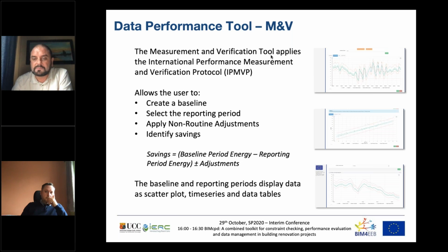The options you see on the right, in the middle, show a simple linear regression model, and the user has 2 options: when they look at the data, they can see it's either simple linear or change point based on how it's modeled, and they can save that baseline so that when they come back after the renovation, they can run the reporting period analysis, which will give them the approximate savings between the baseline and the reporting.